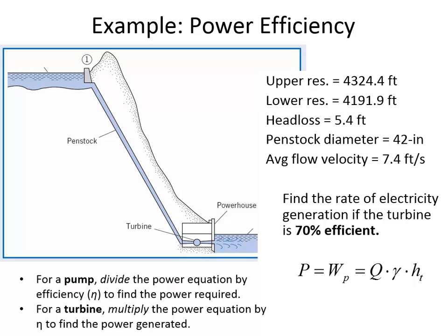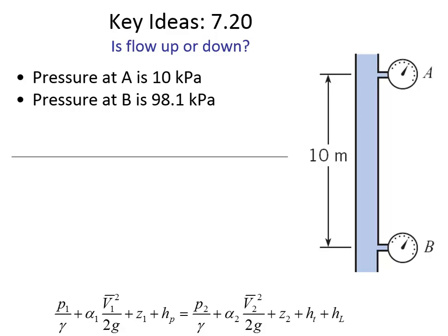And so what we have here in the eastern United States are called low head dams, because the way you're generating power is by having a big Q rather than a really big H. Out in the western United States, in Colorado, Utah, Arizona, through the Rockies, they have these enormous elevation differences. And to a lesser extent, there are some hydropower stations in Virginia that have a reasonably high head to them. North Carolina. Yes, probably more than anything, a big elevation difference is the most important thing.